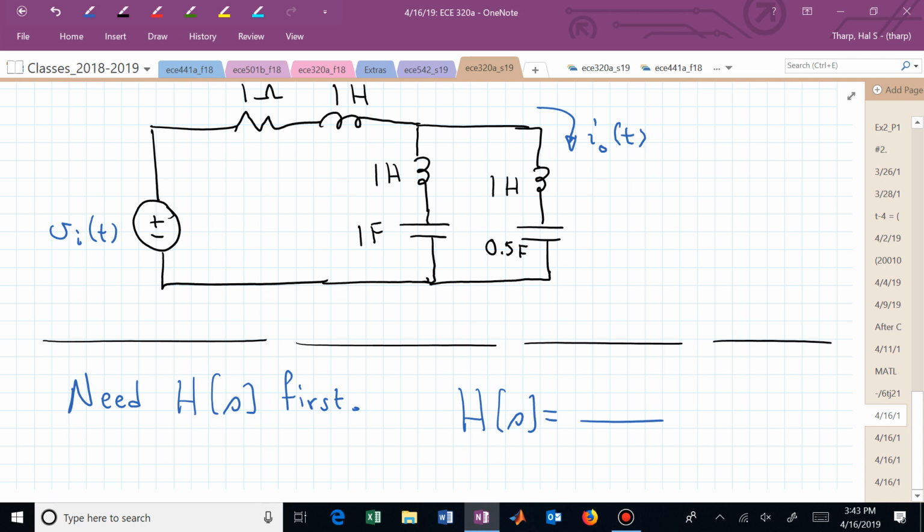At j2. You're going up the jω-axis, and you stop at 2 radians per second, and you look around and you say, okay, how is this transfer function influencing me now, standing at this point at 2 radians per second? And that's what happens when you evaluate H(s) at that location on the imaginary axis, j2. In order to get that, we need to first find H.